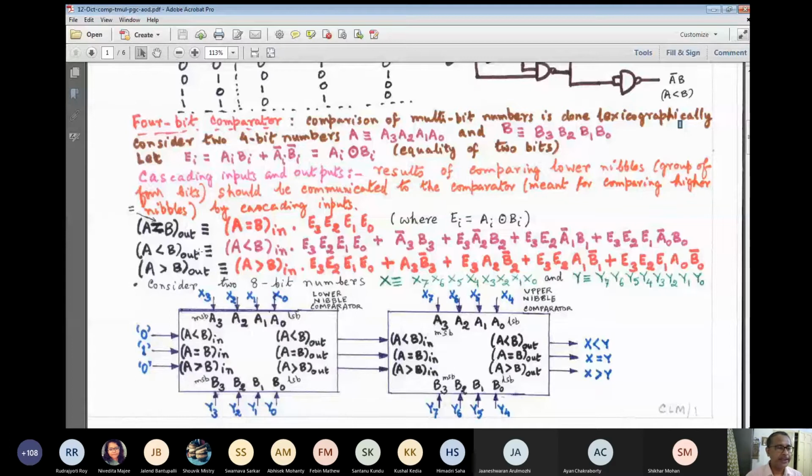Here we can surely say that, having compared up to say 12 bits, that means up to A0 to A11, B0 to B11, as we know about the comparison of A0 to A7, B0 to B7 at these 3 inputs, if this becomes 1, I know that the result of comparing A7 to A0 and B7 to B0, this 8-bit component on the lowest significant end, is A less than B, then only this becomes 1.